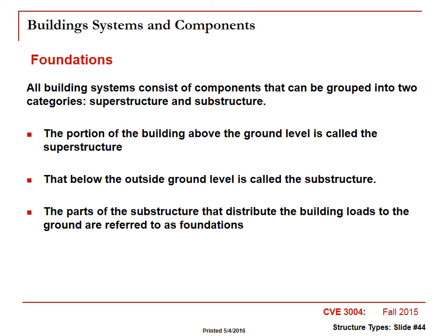Again, the foundations. These are spread footings. These are mat footings. This is the below grade. Typically, we think of concrete type structures. It doesn't have to be concrete, but a lot of times we think of concrete. And the foundation is basically what's going to accept the loads from the building and transfer them. It's going to be the last mechanism, if you will, in the transference of loads ultimately into the soil.